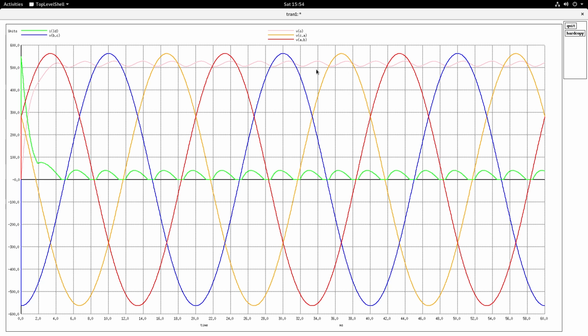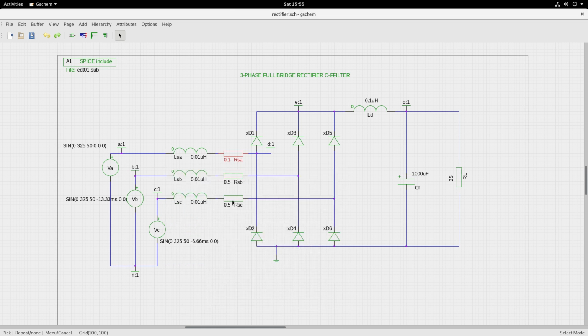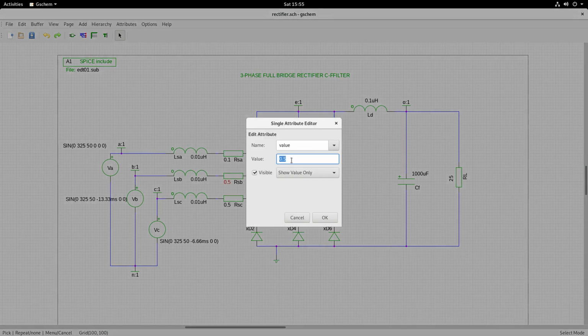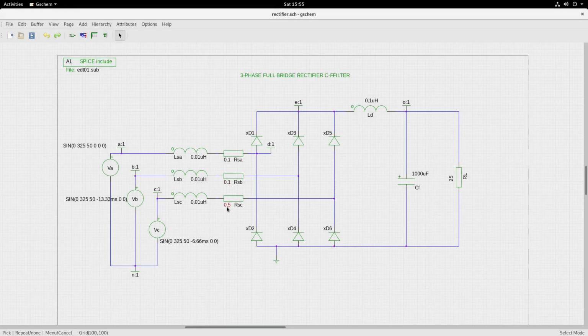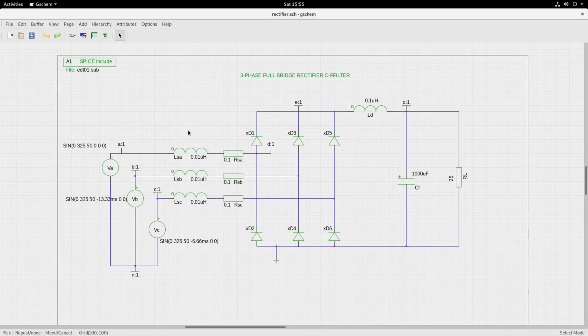If you would like to see what would be the inrush current limit when we reduce the surge limiting resistor value, then you will see that the inrush surge limit can go to very, very large current values. Let us have a look at that also. I will change these values to 0.1 ohms, almost no surge limiting resistor there. This 0.1 ohms would represent all the line resistances and no more.